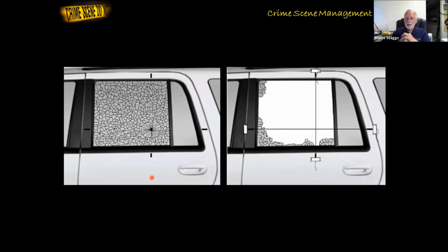This is a side window, and they are tempered glass. Now with tempered glass, when it breaks, it breaks into small chunks, or it cubates. Other glass, like normal residential window glass or in a picture frame, breaks and it can be really hazardous, all the sharp pieces. But on cars, there'll be tempered glass. On a sliding glass door, it'll be tempered glass, and it'll break into pieces like this.